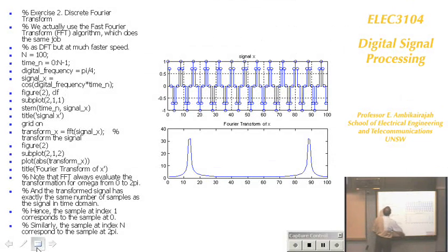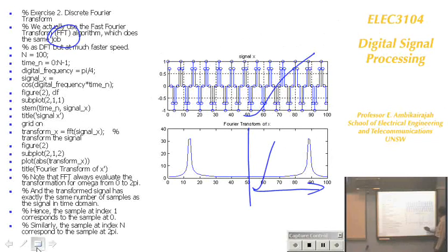So this is a typical example of a fast Fourier transform implementation of a signal, and here's your signal. You use the fast Fourier transform explained there, and these are the two frequencies you have occurring here. This has now become K. K is your frequency position, and now you can translate K into frequency. So if K is 5, then I will say 5 times delta F is my frequency. Delta F is my frequency resolution.